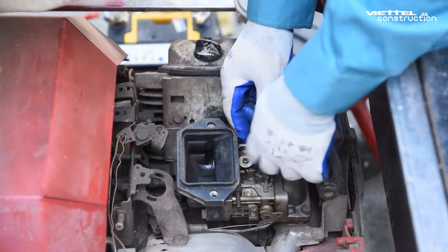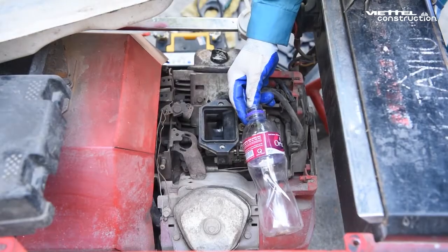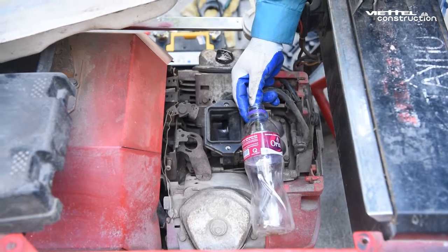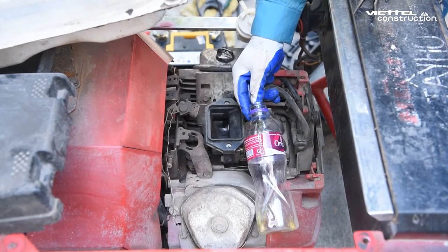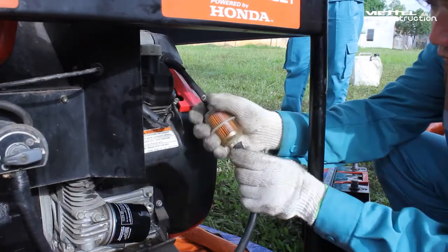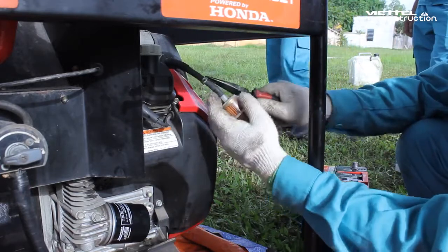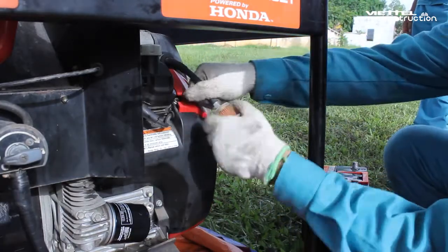Remove the fuel pipe at the carburetor. Perform machine operation to check whether the fuel is draining out or clogging in the hose. If the fuel is clogged, check the fuel pipe and filter for fuel. Note: when installing the gasoline filter, you need to set the direction of the arrow on the gasoline filter towards the carburetor.